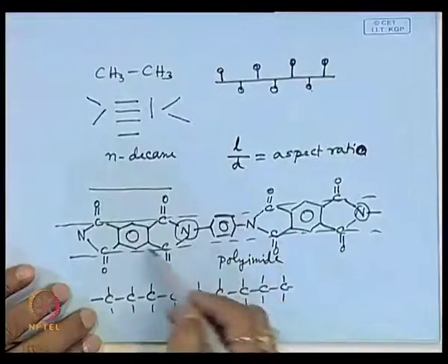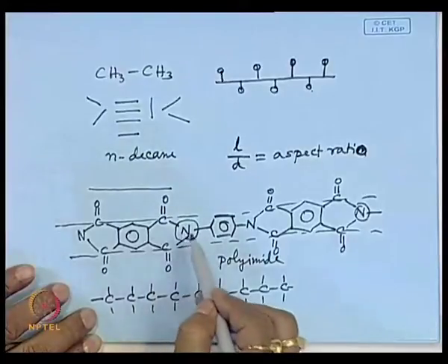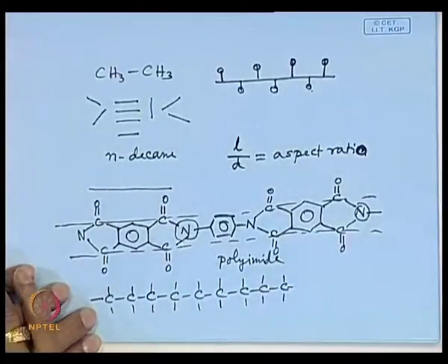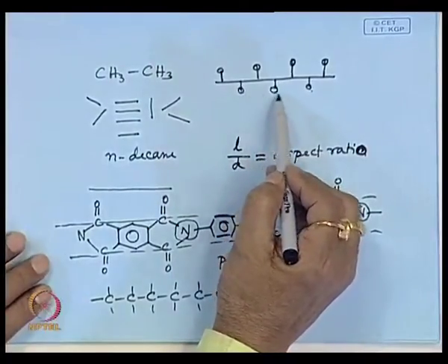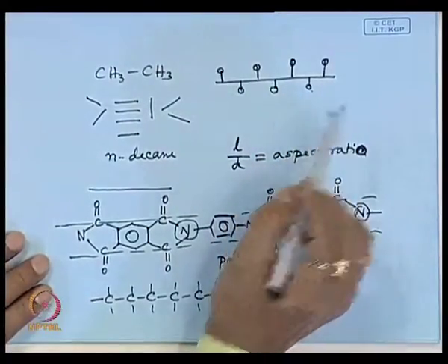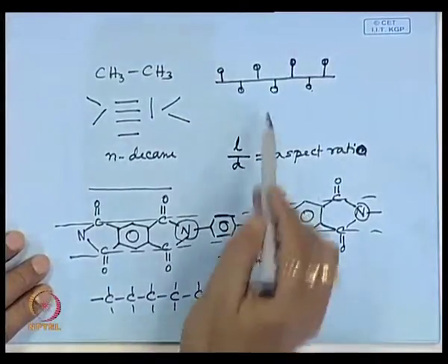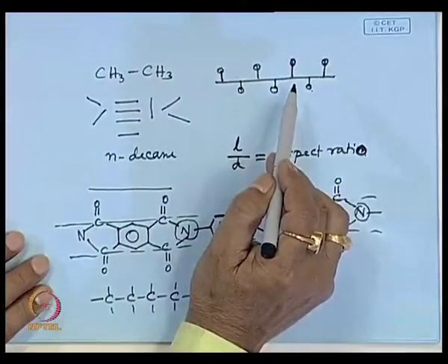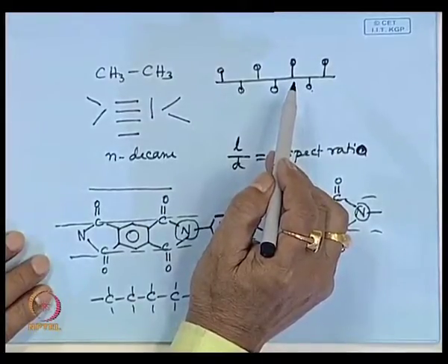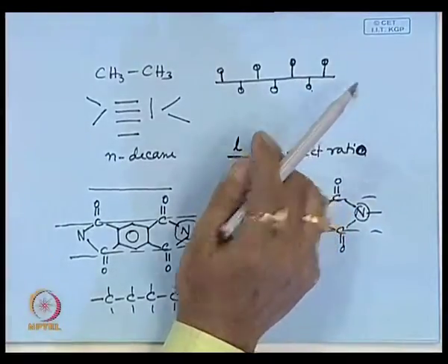That means, you can have a polymer where mesogens can be placed along the backbone chain. You can have liquid crystalline polymers where mesogens are placed as pendant groups. You can have a polymer where both these backbone mesogens as well as pendant mesogens can contribute to this mesophasic structure configuration, liquid crystalline behavior.